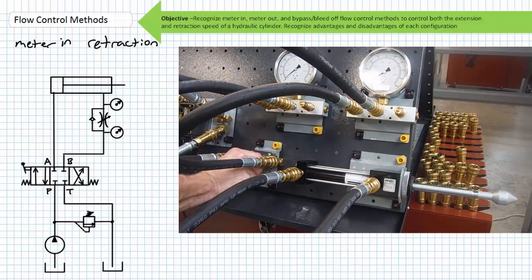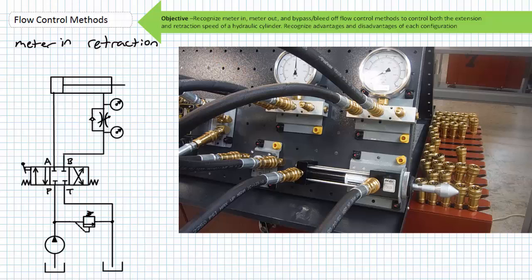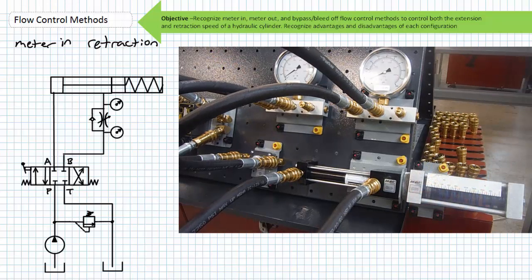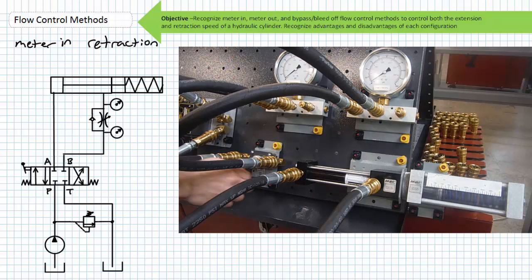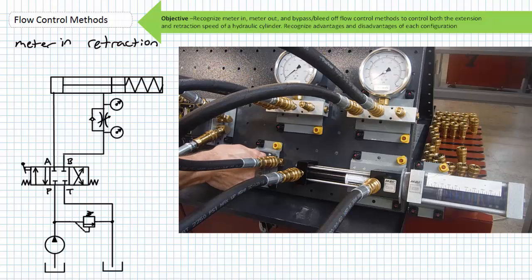Additionally, notice the pressure gauge I've placed on the upstream side of the flow control valve rises while it is retracting. This is the pressure rise due to the pressure differential created by the narrow passageway. Somewhere in here is a point when both extension and retraction are occurring at the same speed.